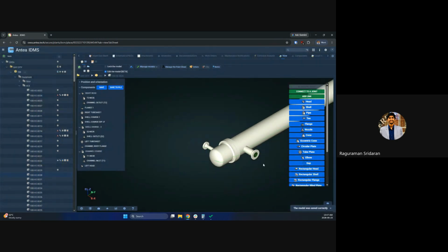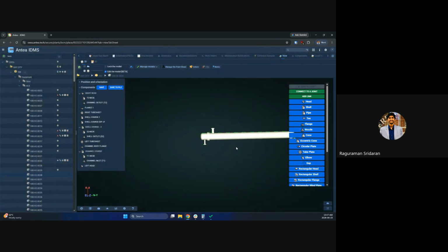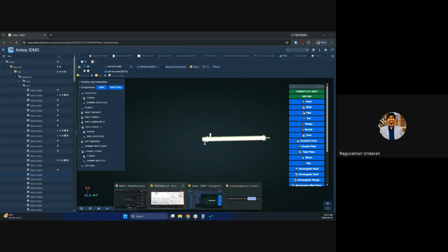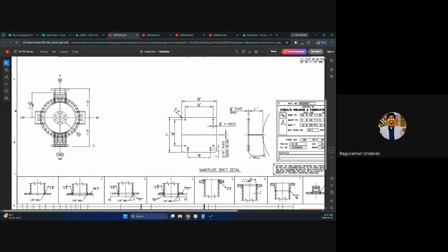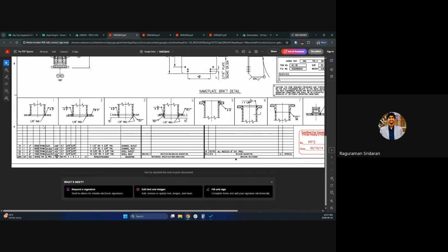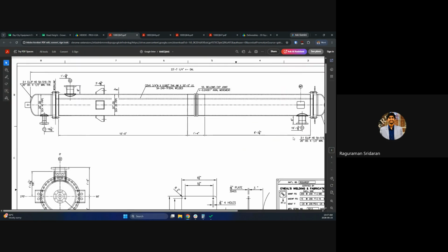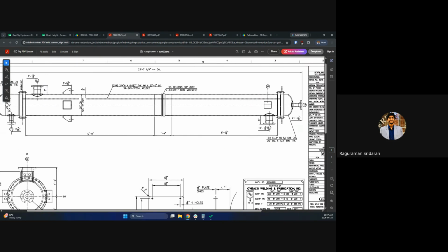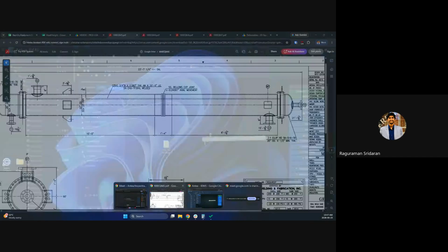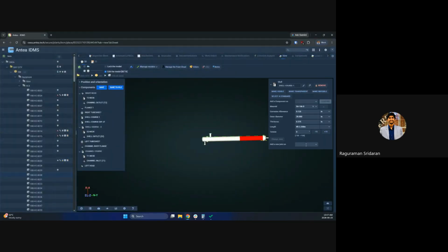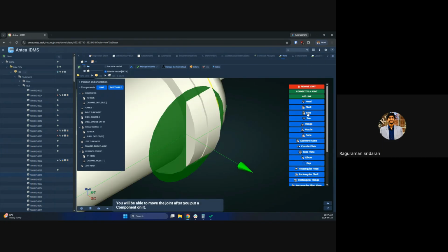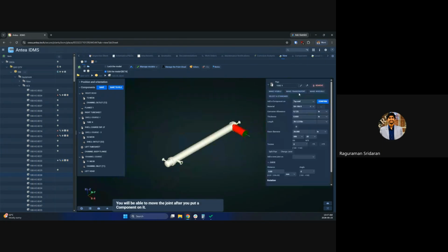So now we created the T1, and we have left this S1. Once we finish S1, then it should be good, I guess. So let's see. S1 is actually placed here on the shell course 1. For the outer wall, we select the shell course that we want to place the nozzle on, and then select outer wall and select the pipe.